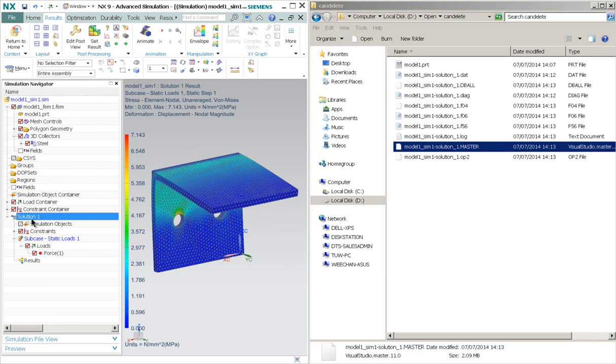Please bear in mind that a restart analysis is kind of advanced stuff in a CAE application, where the user will need to have some basic experience in reading the solver keywords. When it comes to restart analysis, we will need to do some keyword editing using word processing programs such as Notepad or other free software such as Notepad++.